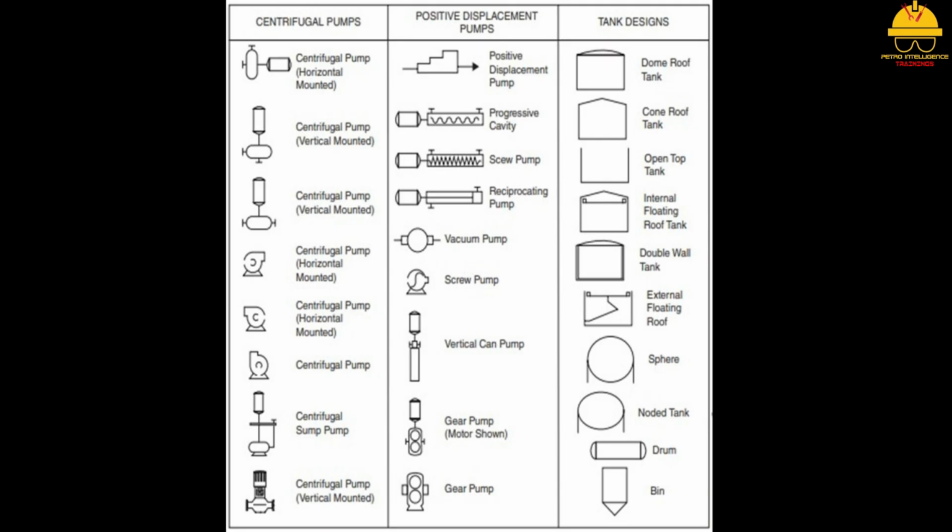Pumps come in 2 basic designs, dynamic and positive displacement. Dynamic pumps include the very popular centrifugal pump and axial pumps. Positive displacement pumps have 2 categories, rotary and reciprocating. Reciprocating pumps typically include piston, plunger, and diaphragm. These operate with a back-and-forth motion, displacing a predetermined amount of liquid.